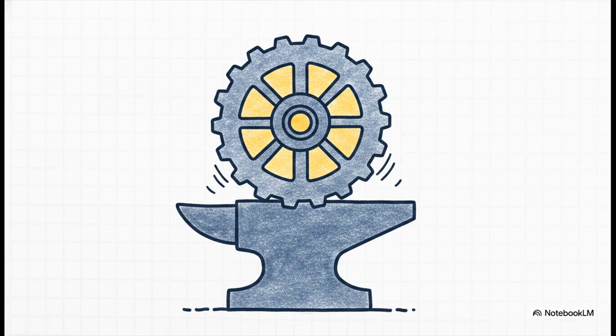Three-phase equals constant power. That single physical difference, the complete elimination of the power pulse, is the exact reason generation, transmission, and distribution all run on three phases. Think about it. When you're generating hundreds of megawatts or running massive industrial machinery, those single-phase pulsations would create shaft vibration and noise so severe it could literally destroy the machines. Constant power is the structural bedrock of the grid.